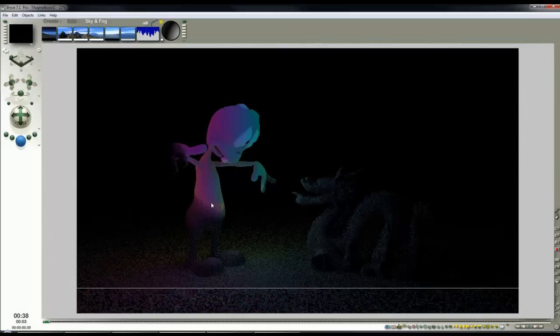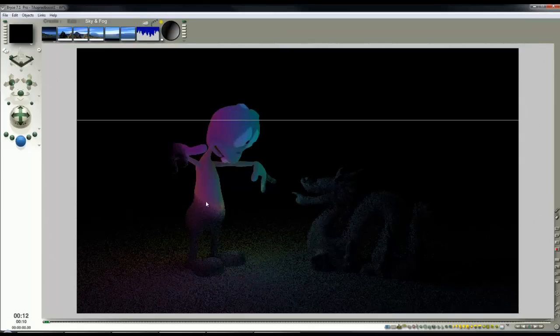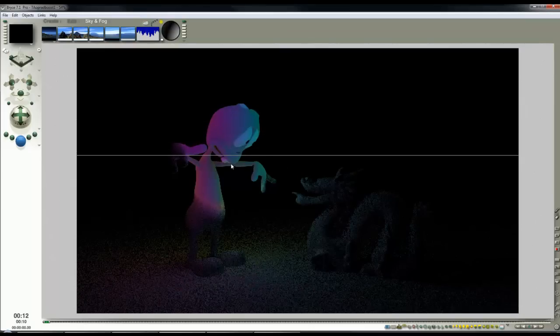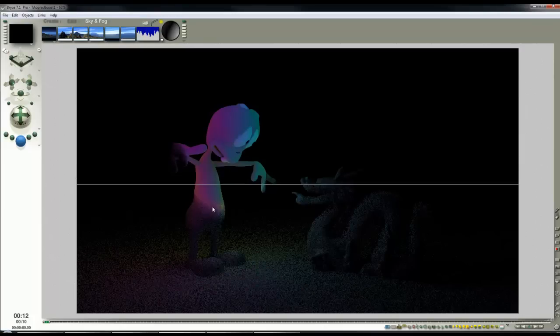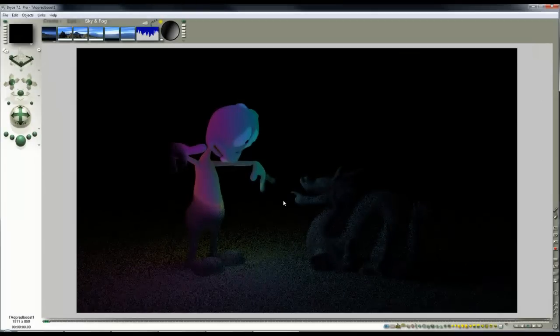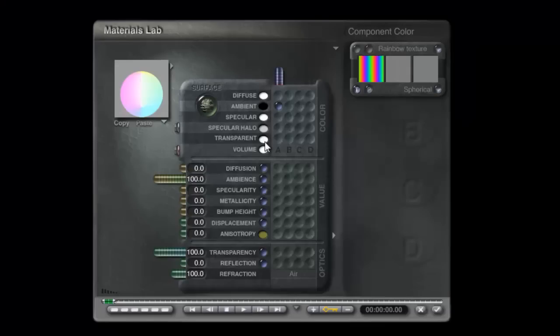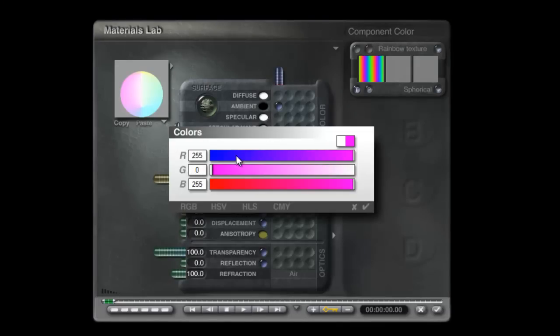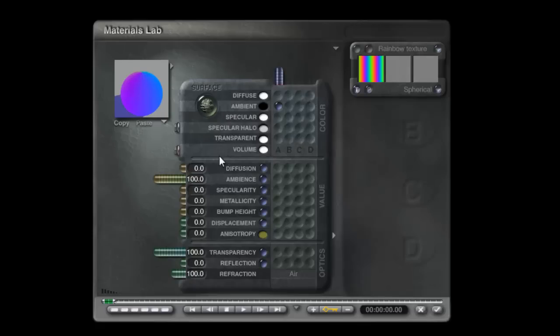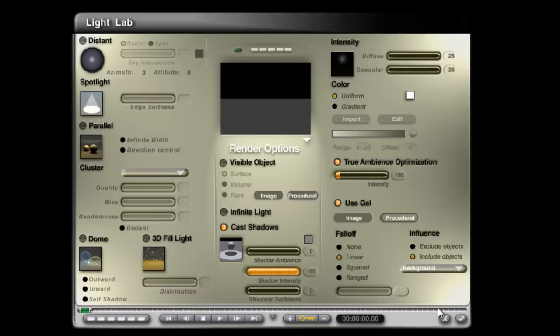So this transition zone here is from the inside of the light source to the outside, and there is quite a significant change in behaviour because of this transparency setting. Okay, well, I said that with a confidence that I don't necessarily feel, but you have a look. If we change the transparent colour to, let's say, blue, for example, so now this will act as a filter, and we've got rainbow coloured light being transmitted in, and it's going to be filtered on its way out.